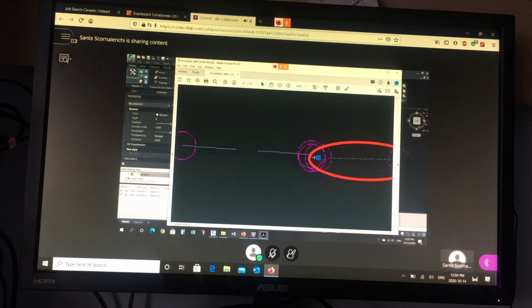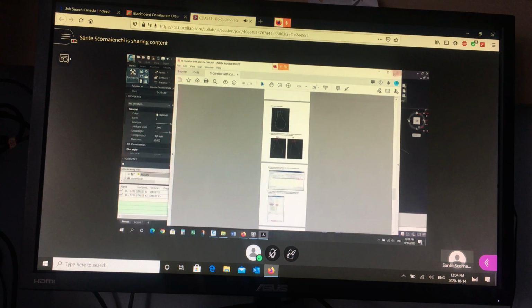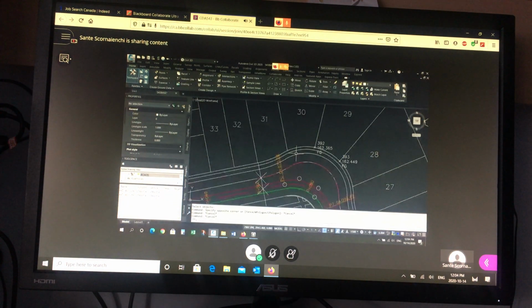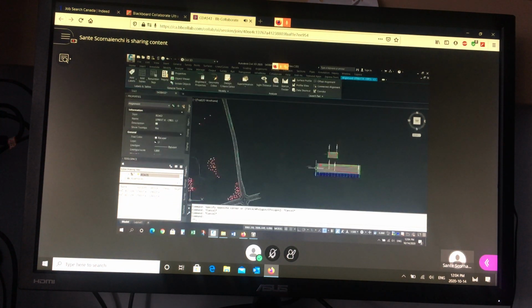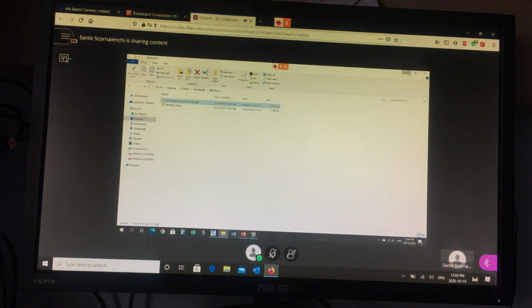So you have to be consistent. If you draw your alignment at the asphalt edge, then the assembly point represents the asphalt. If you draw your horizontal alignment at the gutter, then the assembly point represents the gutter, and then you have to proceed accordingly. Okay? So be careful about that. It doesn't matter how you do it. It really doesn't matter whether you do what I did in class or whether you follow this procedure here as a guide. You're going to get the same model, but you have to be consistent. Once you commit to the gutter, if this is your gutter, then your assembly has to be in the gutter. If the alignment represents the edge of asphalt, then your assembly is here at the edge of asphalt. Okay, so you just need to be consistent with that, that's all. It's not wrong, it's just different.